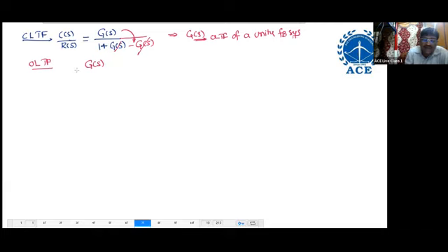No term in the denominator means 1. Just add the numerator term in the denominator. Then it will become what? Closed loop transfer function. That means when you want to get closed loop transfer function, add the numerator term in the denominator.